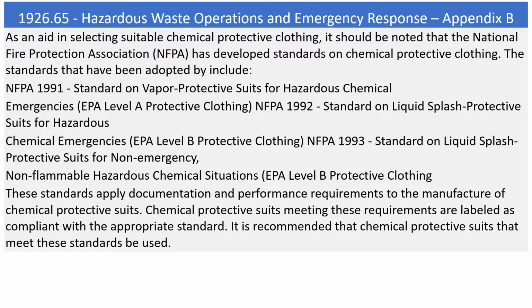As an aid in selecting suitable chemical protective clothing, it should be noted that the National Fire Protection Association, NFPA, has developed standards on chemical protective clothing. The standards that have been adopted include NFPA 1991, Standard on Vapor Protective Suits for Hazardous Chemical Emergencies, EPA Level A Protective Clothing; NFPA 1992, Standard on Liquid Splash Protective Suits for Hazardous Chemical Emergencies, EPA Level B Protective Clothing; NFPA 1993, Standard on Liquid Splash Protective Suits for Non-Emergency, Non-Flammable Hazardous Chemical Situations, EPA Level B Protective Clothing.